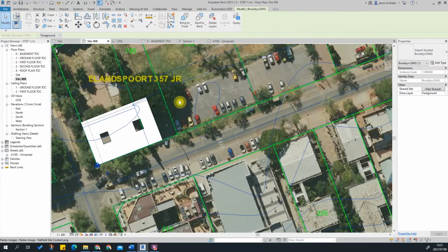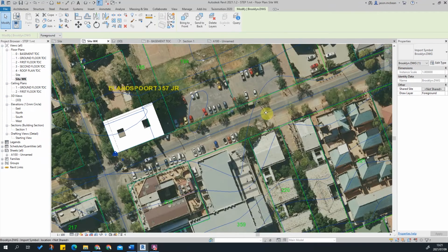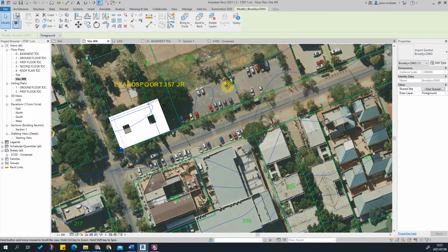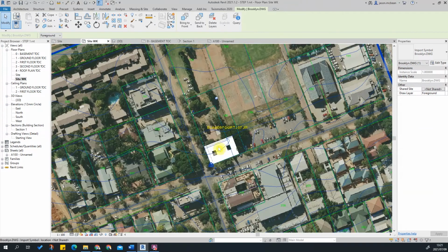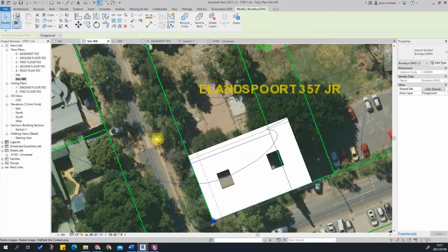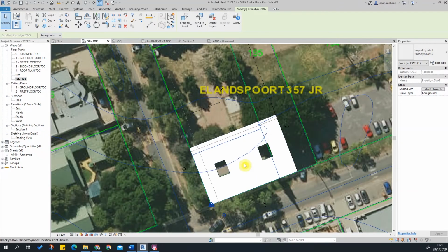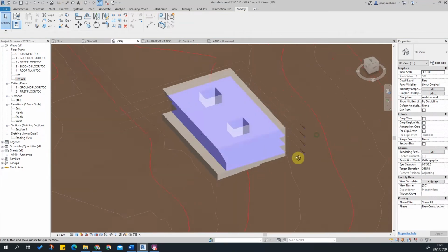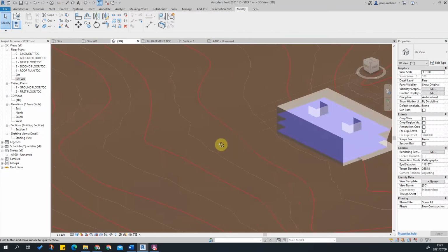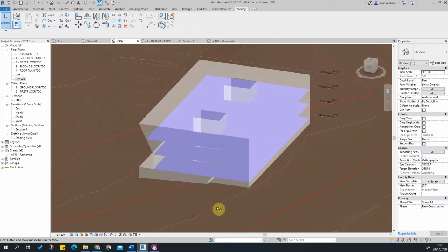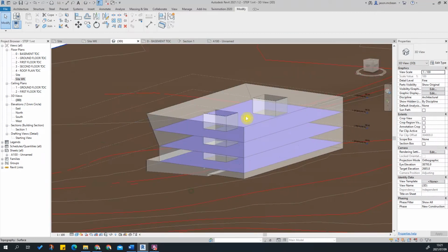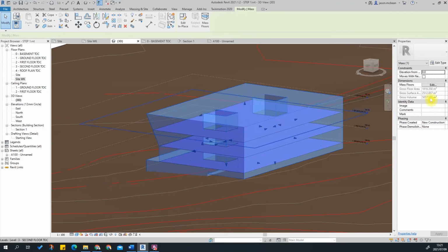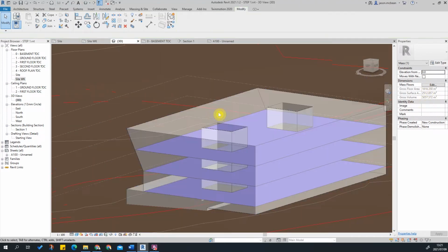But here we're going to start establishing the parking area. Okay, and we're going to start establishing the access to our site and how the back of our site will work. I've used a mass in this instance, so I've got two options. By now you should all have a mass of your design project which you can use, so that's exactly what I've done. I've created a basic mass. The reason why I've created a mass as well is because it will give me the total gross volume and floor areas. Okay, because you're going to need these values later on when we do our calculations.